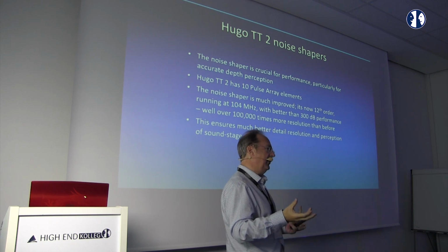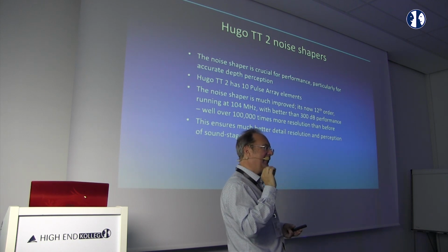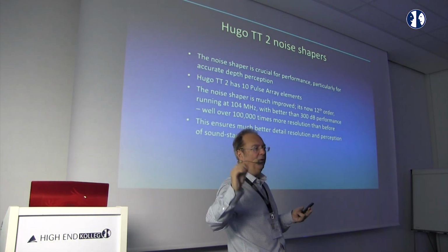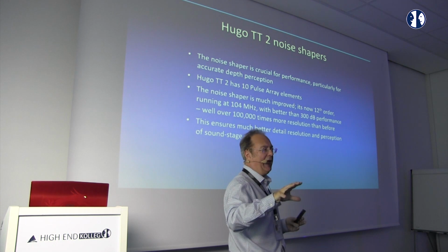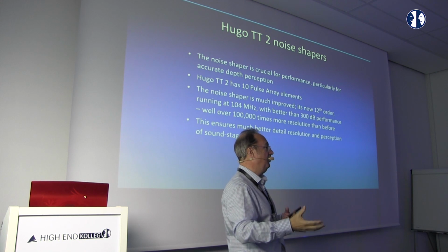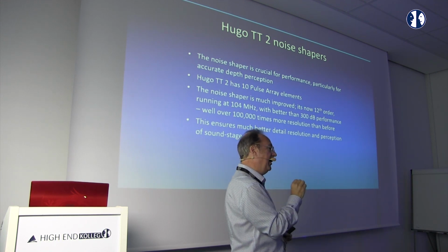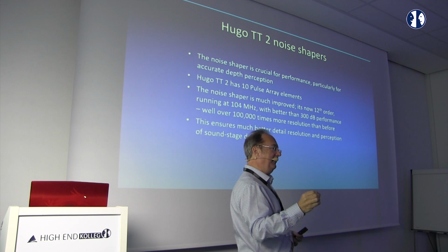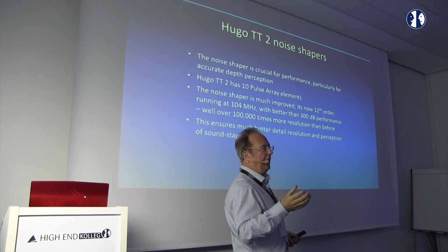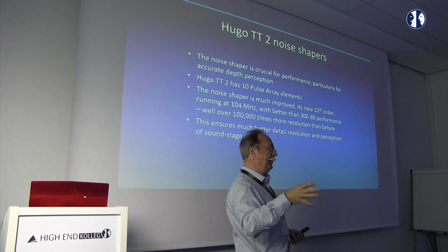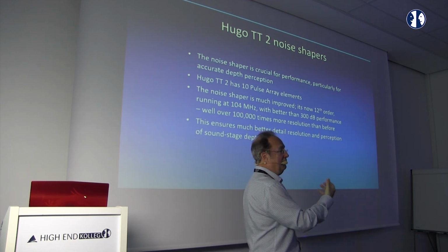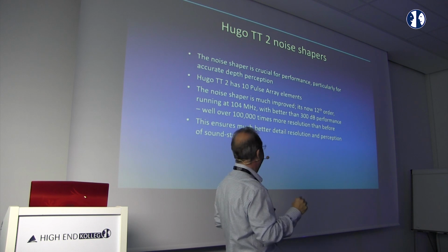What I failed to appreciate was if there is the tiniest error, and even if the error is at 0.0000001 dB, it doesn't matter how small that error is, the brain sees it as a truncation in depth, and that's really very, very weird. What I found with Dave was that you needed 350 dB performance. That's a 64-bit level of accuracy. You can actually measure 350 dB performance when you're doing a Verilog simulation. So I can design my noise shapers and actually measure this performance, so I know it's accurate.